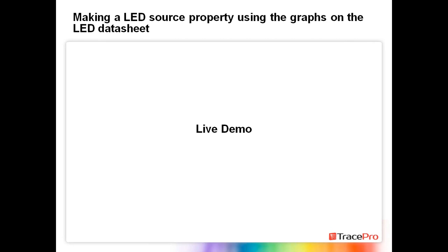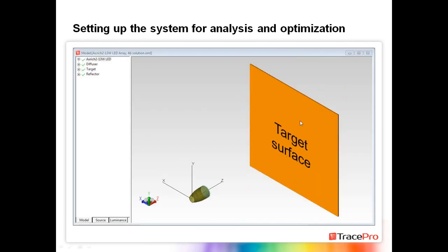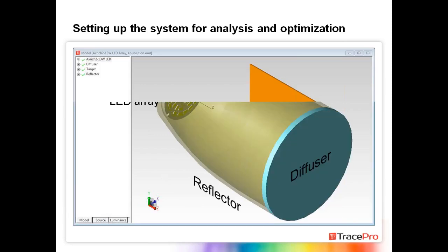And this array had 30 LED chips, and there was 1,000 lumens. So it's 33.33 lumens per chip, approximately. So that's what I'm going to set it up, because I'm going to apply it to each one of those 30 surfaces. So when they're totaled up, they'll produce the 1,000 lumens. And then we just export the property to the software, and then it'll be saved as part of the database and can be used at any time in the future in any models.